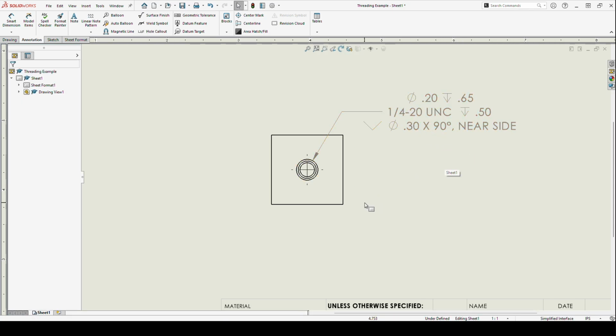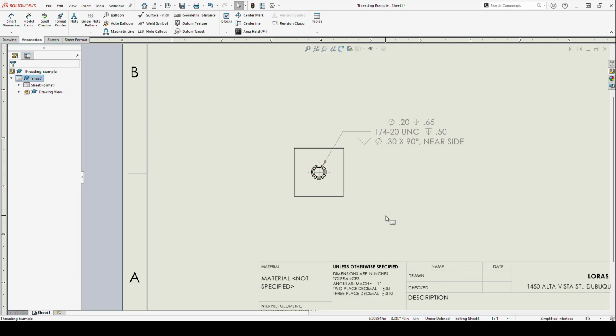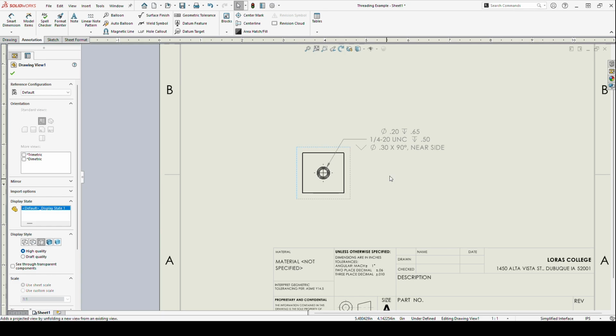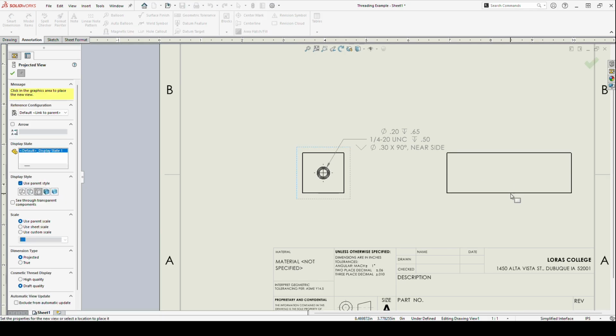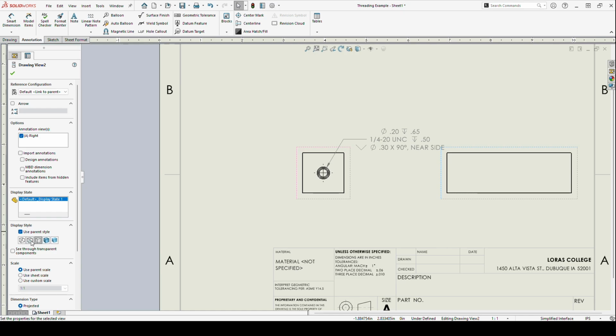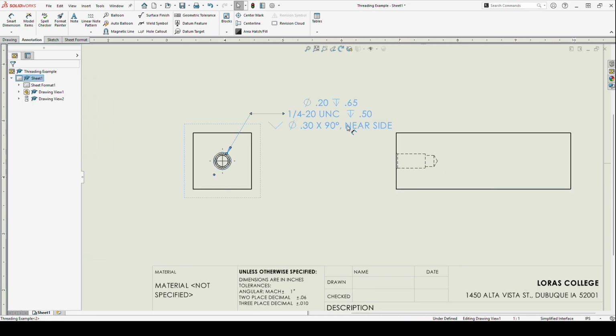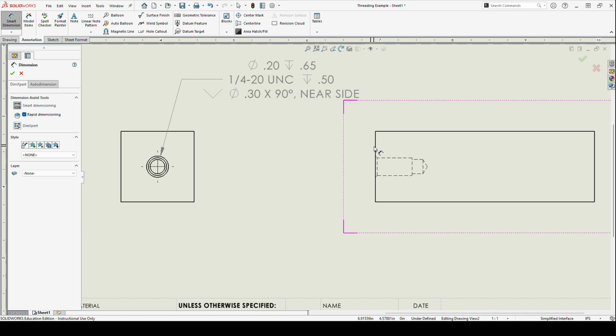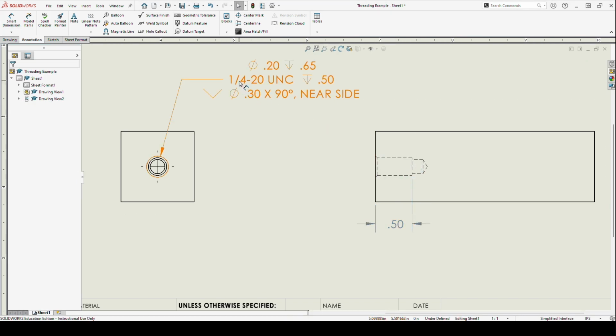And that means that I don't have to figure out how to create a section view in order to add all of this definition. But as we can see, if we were to add all of this, and I go ahead and show hidden lines, again, remember, we'll be talking shortly about how we don't dimension to hidden lines. But if I go through, I can add a couple dimensions here, and I am seeing that I am indeed 1/2 inch down for my threading.